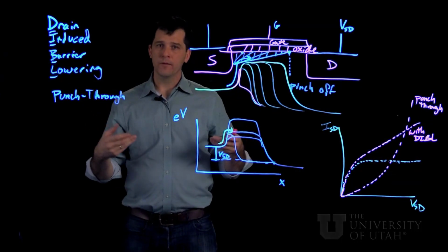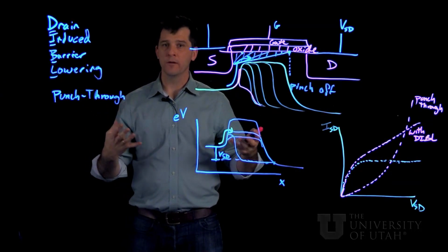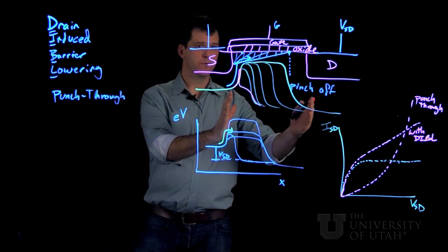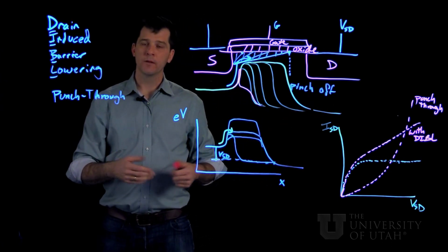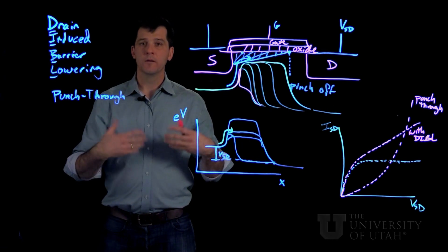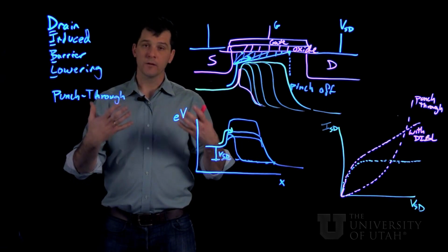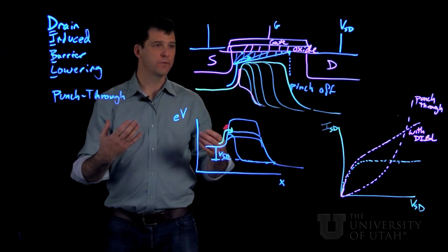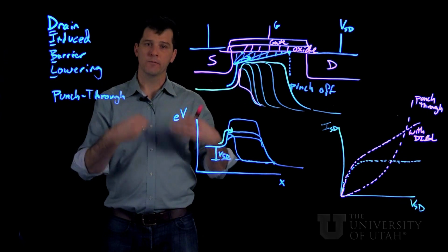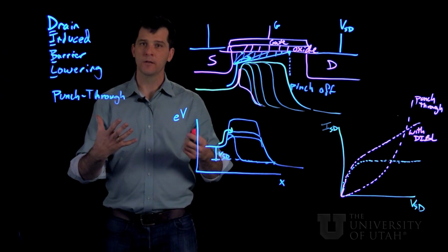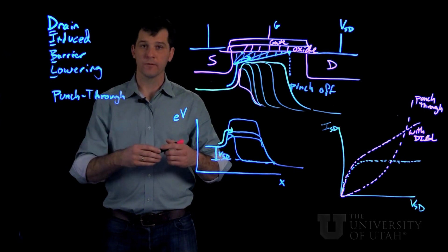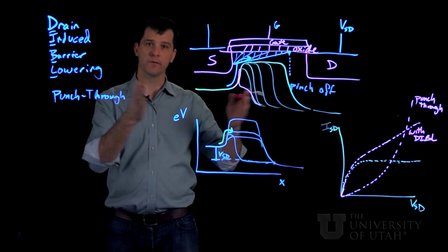So as transistors have gotten smaller and smaller, scaling down to the tens of nanometer sizes for the lengths of the channel, these effects have become really critical, and in fact, you can no longer design MOSFETs as sort of a one-dimensional structure. It really has to be considered as a three-dimensional structure in terms of predicting the performance characteristics and what dopings and physical sizes will be needed.